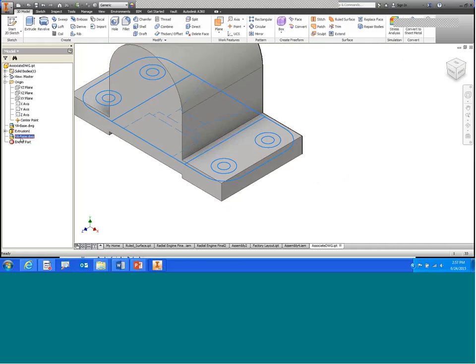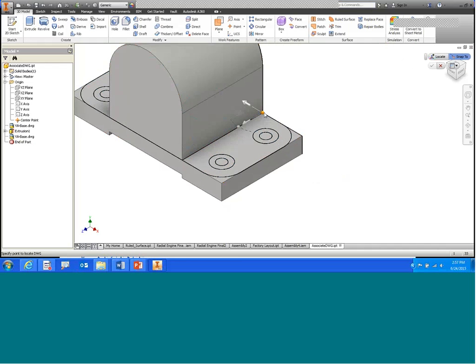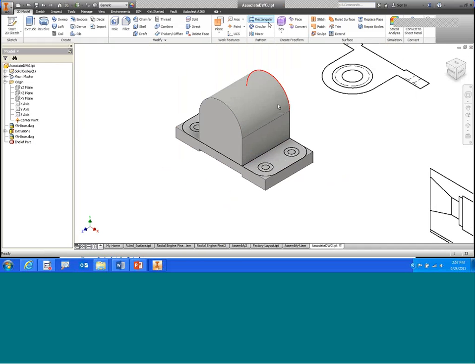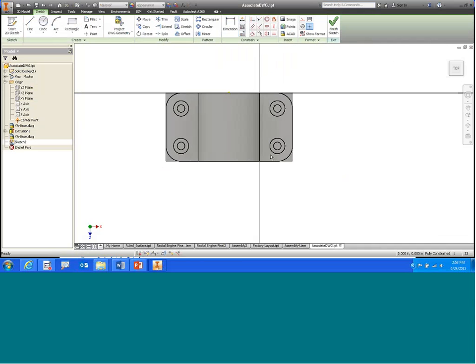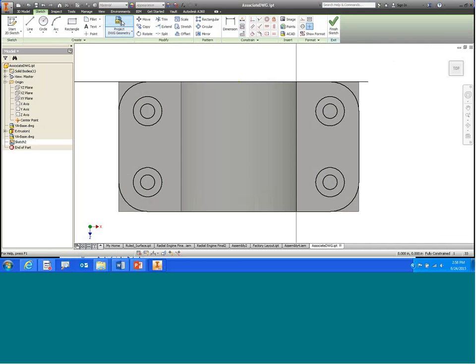Okay, why is that not translating there properly? Translate, there we go. Locate here, snap to this very corner. There we go. So that looks perfect. And again, I'm going to start a sketch. I'm going to create the sketch on this plane. And when I do so, I can go in again and project some of that AutoCAD data directly in.